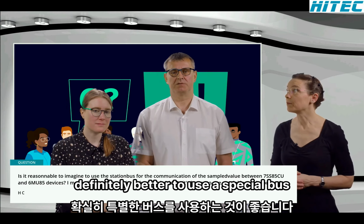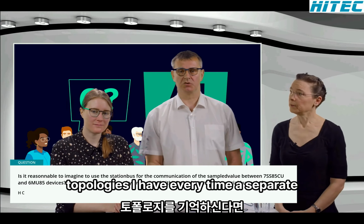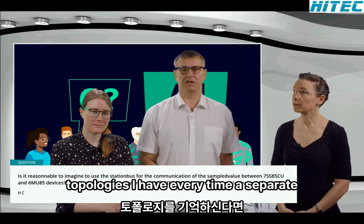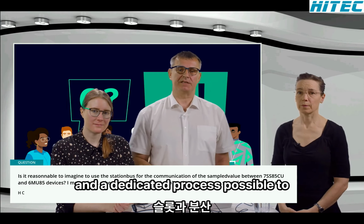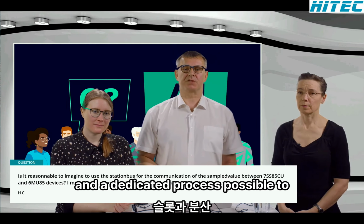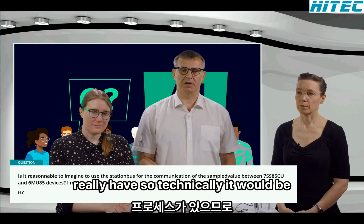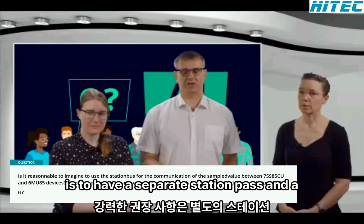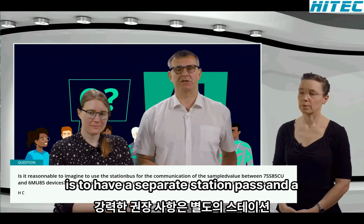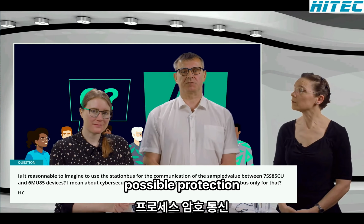It's definitely better to use a special bus. So if you remember all my communication topologies, I have every time a separate communication slot for the station bus and a dedicated process bus for the distributed busbar protection. Technically it would be possible, but the strong recommendation is to have a separate station bus and a separate process bus for the communication for the distributed busbar protection.